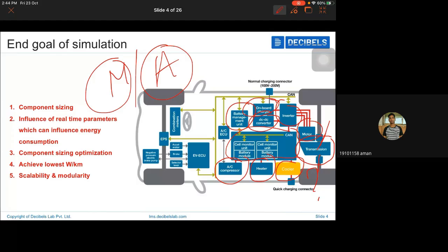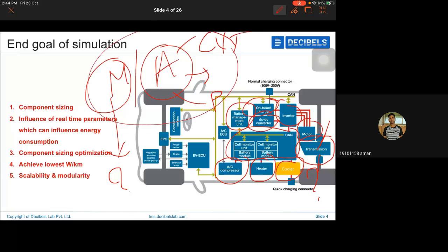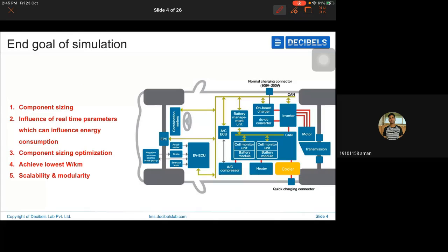But again, in automatic transmission, you have something like CVT, right? You have hydraulic based actuation systems, and planetary gear systems come into the picture. What type of transmission should you select? For this powertrain, what type of configuration will fit in? Then on top of it, what would be the gear ratio required for this vehicle, maybe if it's a two-wheeler or a four-wheeler, truck or bus segment or something like that, right? All these things we study as a part of this activity, where we will be able to understand what the transmission should be.